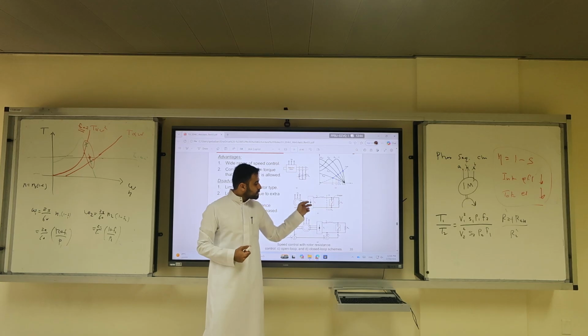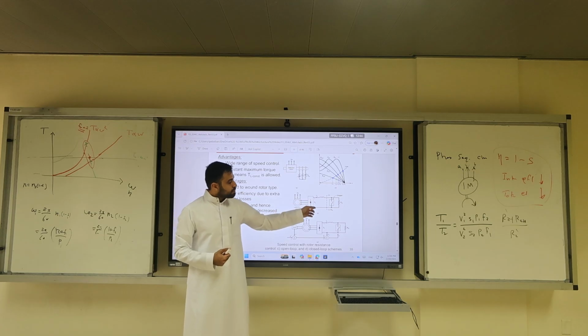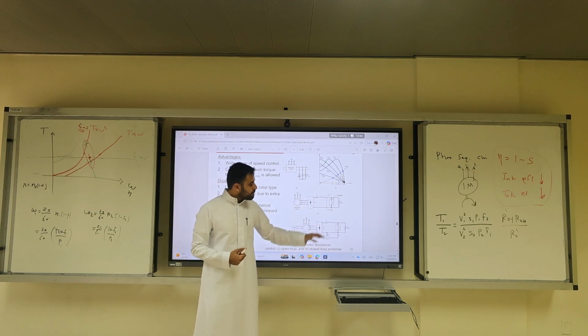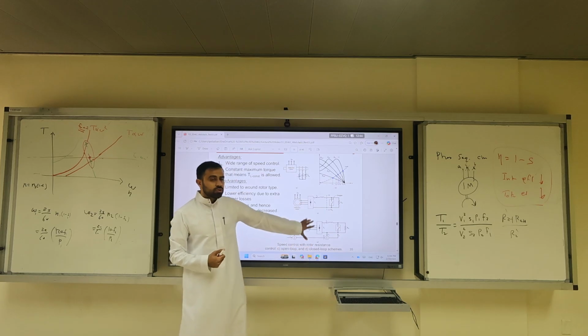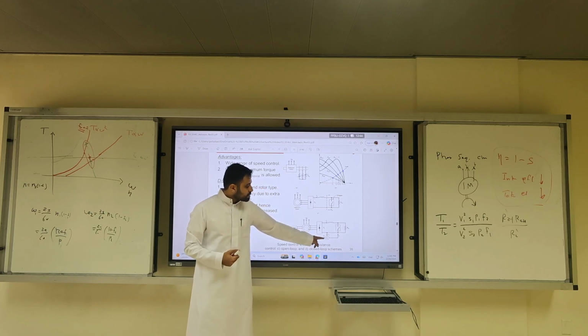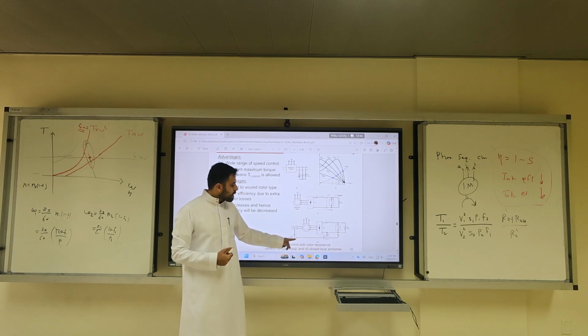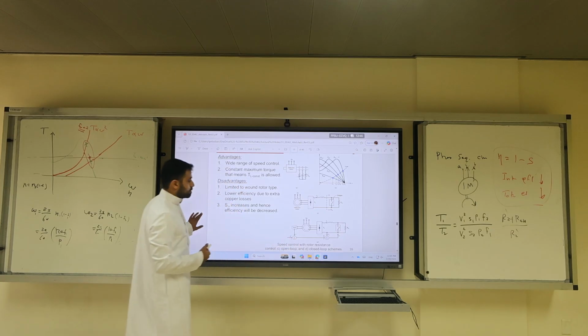So how do you control that using this device, which is the thyristor? Is this a thyristor? Yes, it's a thyristor, a silicon controlled rectifier. The goal of this thyristor is to control the whole system, which is a chopper. You can have a closed loop feedback. This is not required, except you should know the block diagram. You take measurement alpha, which is the firing angle, and you compare the currents and you feed back to the tachometer, which has to do with the speed of your machine.